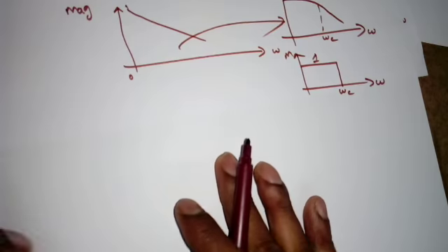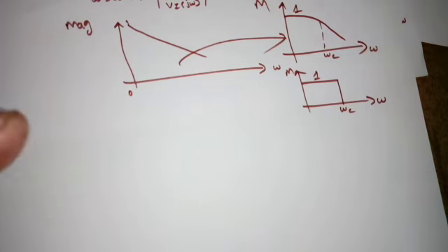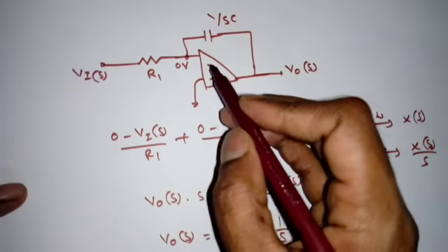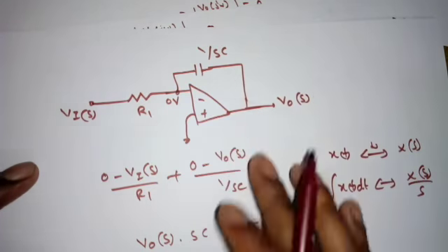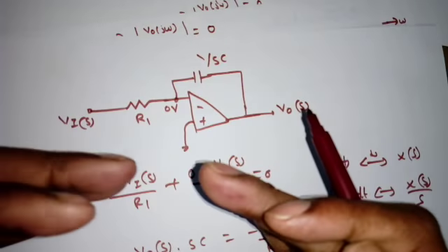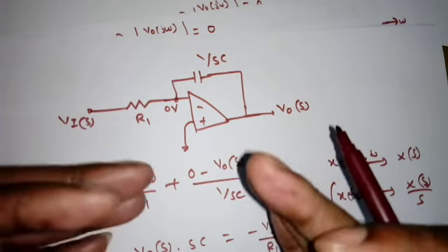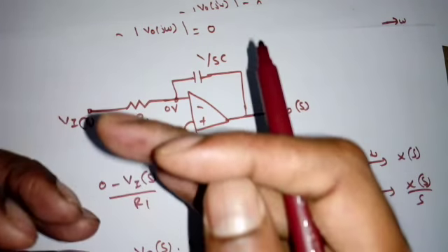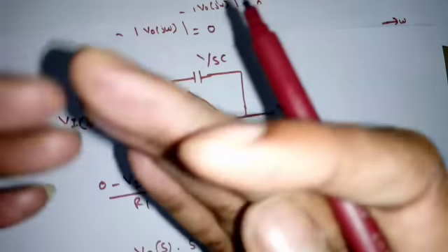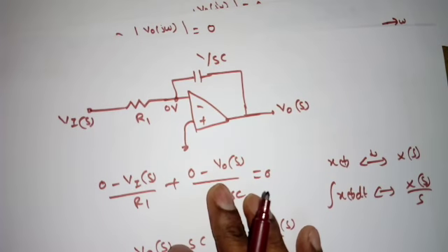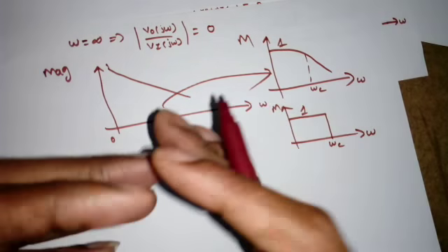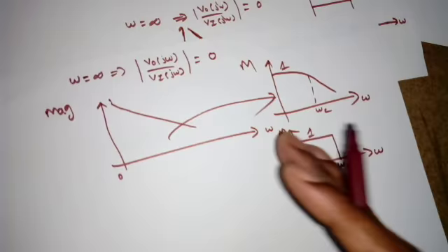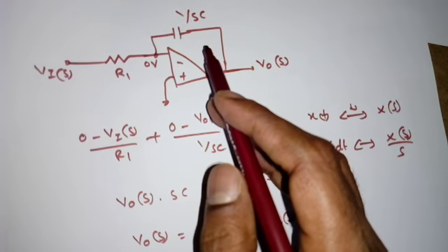So we have to include a resistor in this circuit. So where we need to include it is, we have to include a resistor parallel to the capacitor, right? So that will give the practical integrator. In the previous case, when we included the series resistance, it became a practical differentiator. Now to make the practical integrator, generally when we do in laboratories, I cannot take this circuit for practical purposes.